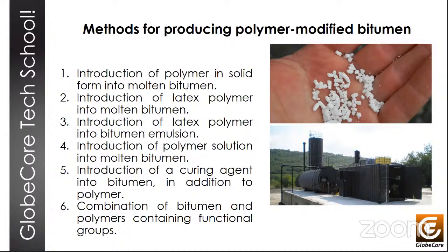So in the production of modified bitumen in batches, one or more mixers are usually used, like two mixers, into which bitumen and polymers are loaded in certain quantities. And then they are pre-mixed and sent to the fine grinding mill, through which they pass the required number of times. So it usually runs in a few cycles. A laboratory test is required to determine the actual number of passes through the mill that is needed. And when the mix has been run through the mill for the required number of times, the mixture is ready for use, and it can then be unloaded to an asphalt plant, to a storage tank, or into a sprayer.